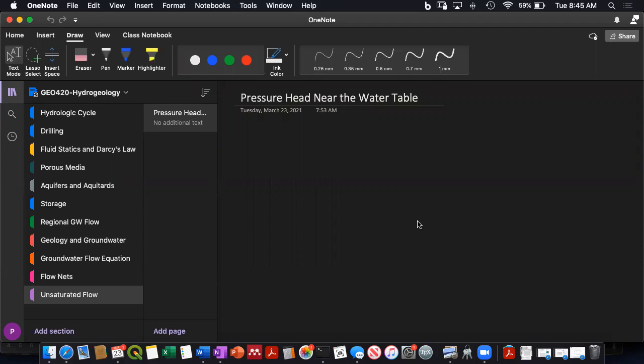Yeah, that's the critical hydraulic gradient. Your job is simply to compare the hydraulic gradient you have to that. Does that make sense? For example, in the field, we measure a hydraulic gradient, or this flow net gives you the ability to calculate hydraulic gradients at a point. And then you compare that to the critical hydraulic gradient.